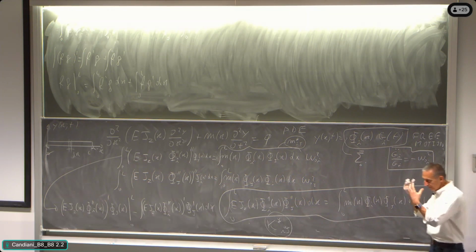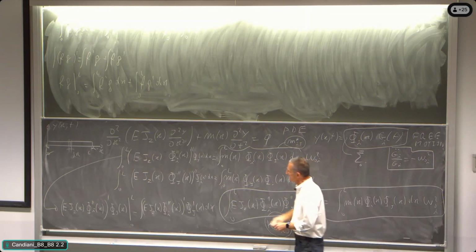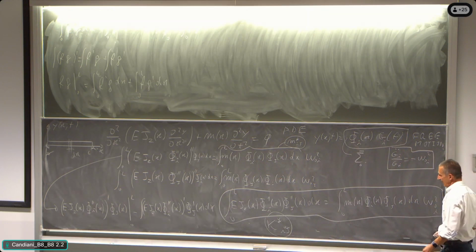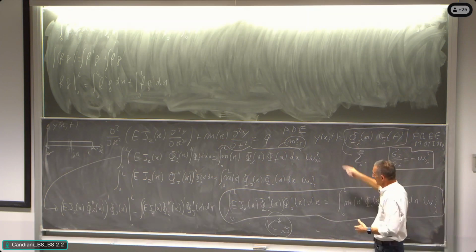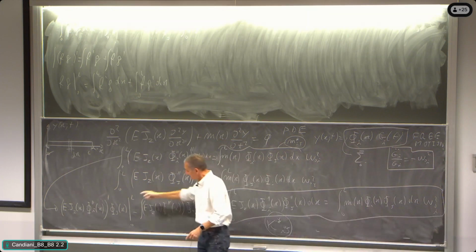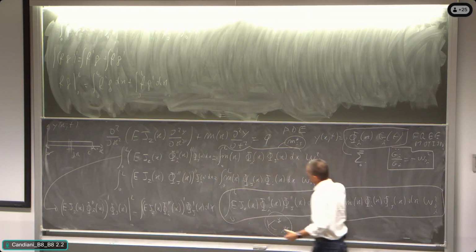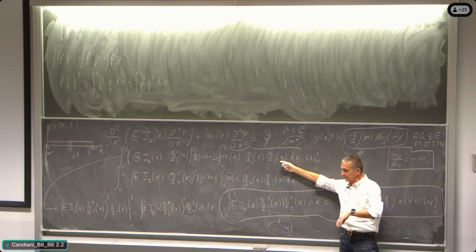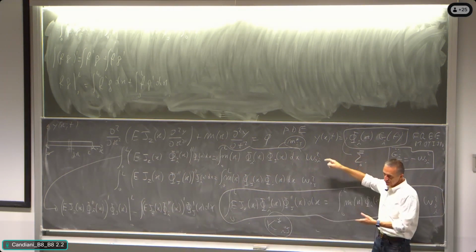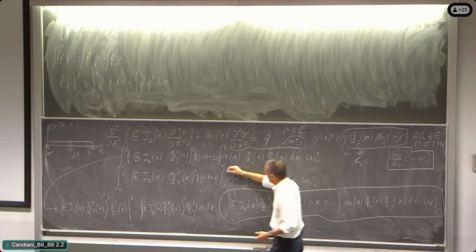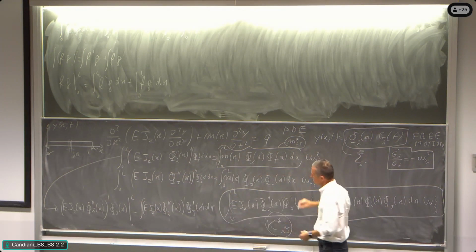But the core of the problem is to start with the partial differential equation, to substitute and to write the functions that are satisfying the boundary condition, and so apply that those functions are satisfying the boundary condition, but we make the trick of multiplying the first equation times the second modal shape, the second equation times the first modal shape, in order to build, on purpose, the modal mass.